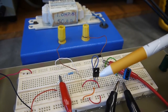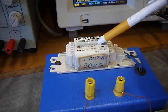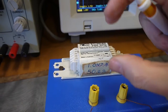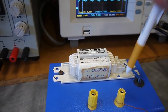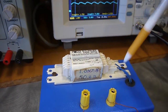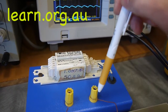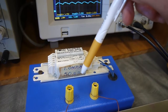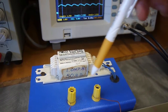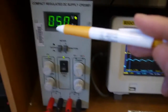So when the transistor turns off, the energy stored in the inductor's magnetic field will collapse, and when it collapses, according to Lenz's law, the polarity reverses. We get nice back EMF, and where we originally had positive here and negative here while the field was building up, now things are reversed. We end up with negative here and positive over here, which adds to the 5 volts which is still supplying